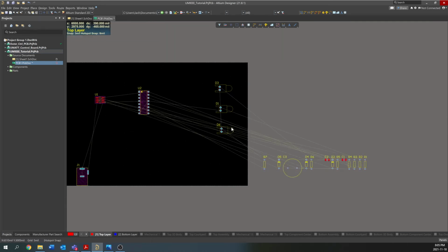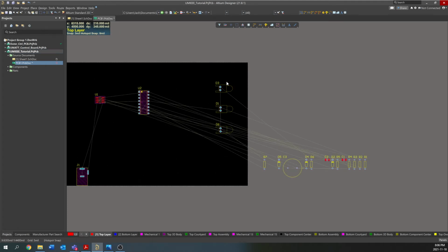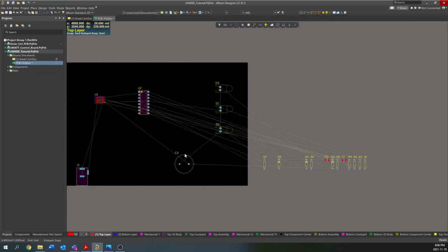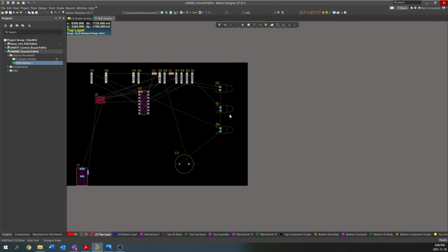Having these outlines kind of simplifies things and allows you to see where components are going to be as you're soldering. This is obviously what the LED actually looks like in the real world. This capacitor is pretty big, probably doesn't actually need to be that big, but again, it comes down to what part you've chosen. And again, you can click and drag groups of components as well.